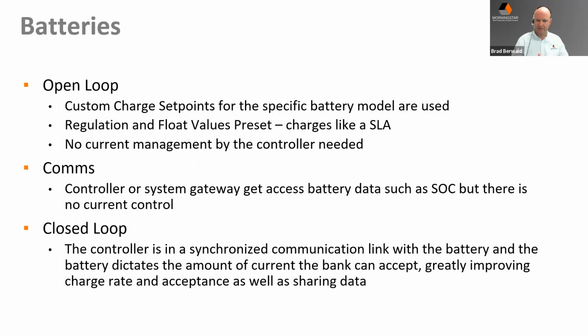It's one thing to estimate state of charge from shunts or other devices. It's another thing if the controller is able to actually ask the battery itself, from its BMS, what its current state is. So we'll be supporting that more in the future. And that's generally done over either RS-485 communications or, more commonly, CAN bus.